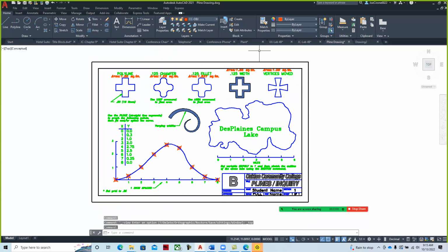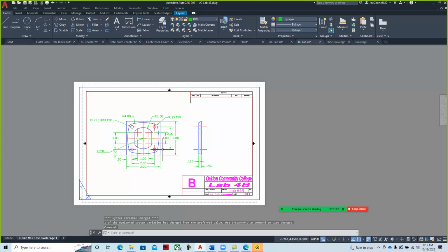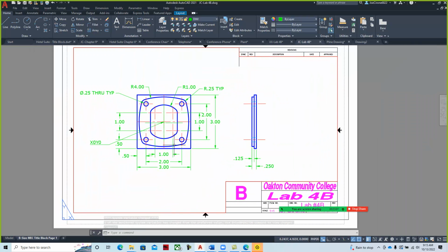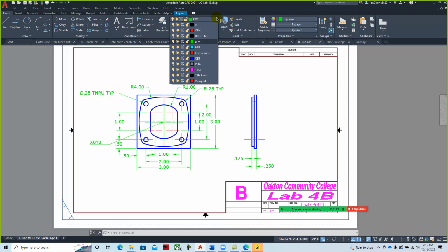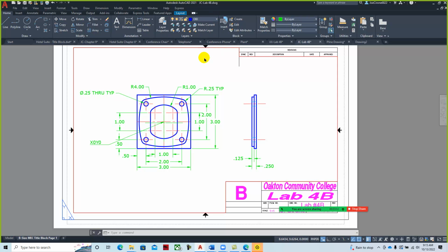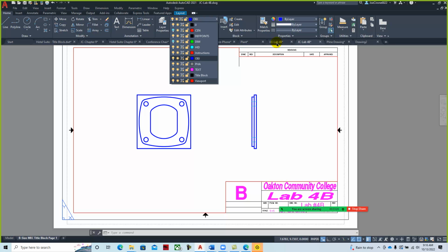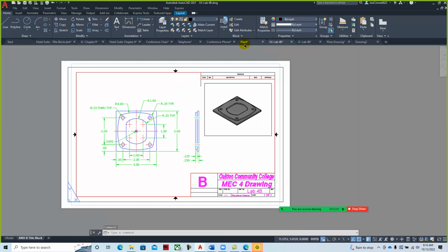And then as we look at the drawings themselves, here's our mechanical drawing. And what we want to do is to use proper layers and line types. And so as we go through and we work with these different objects, object lines are created on the object line layer. Dimensions, I can turn off the dimension line layer, I can see the part. I can turn off the center line layer. And then I can use this on a CAM system to go through and to create prototypes. You can add the solid model as well.